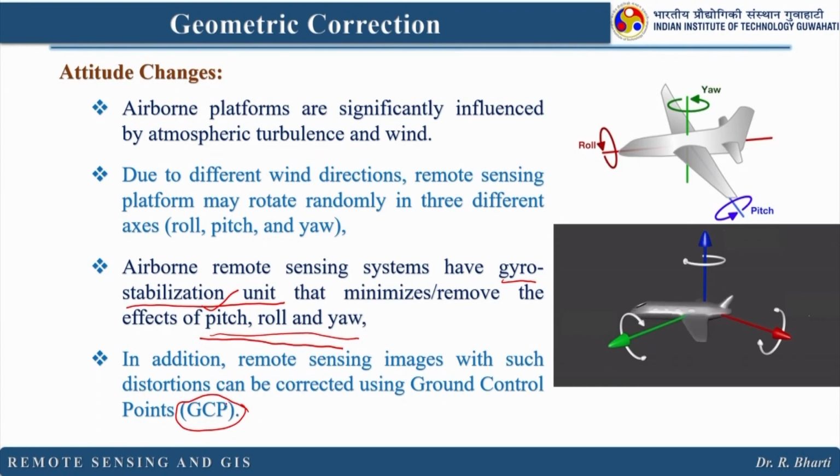In the image, if you know that this pixel is supposed to belong to a forest area, then you can match these ground control points and that pixel location, whether they are same or different. If there is a change in the latitude, longitude value of the image and the ground, then you need to adjust the error of the image, right. Because the measured values, the ground control points, are the true values.